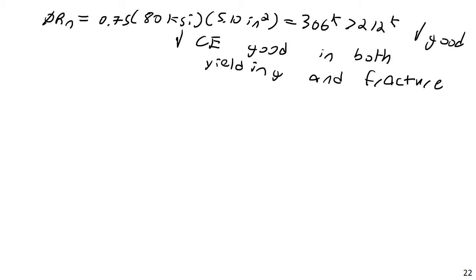Now, if you have a system or a steel member or a frame that is grossly failing, that is failing by massive amounts, switching to staggered bolts is not going to save you. If you are off by 30% or something, and if your member needs to carry 900 kips and you only have a capacity for 700 kips, well, staggering the bolts isn't going to make much of a difference.